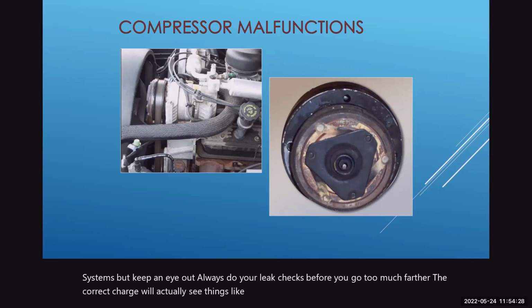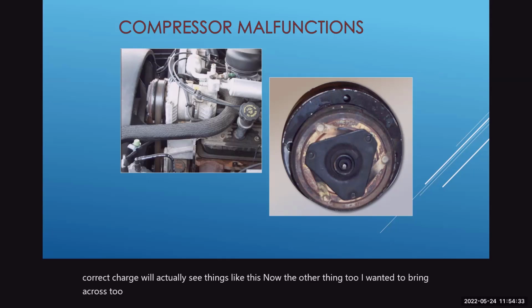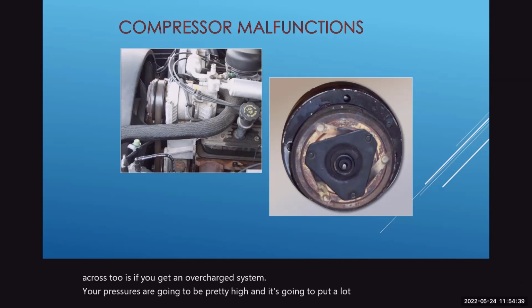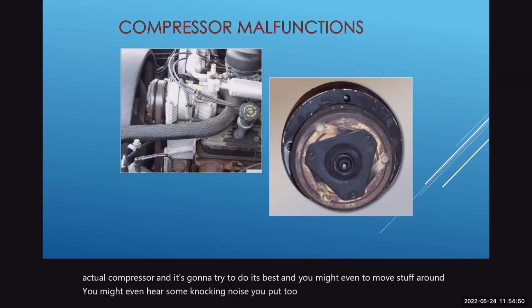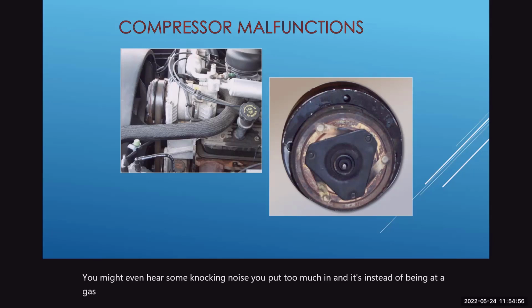The other thing I wanted to bring across is that if you get an overcharged system, your pressure is going to be pretty high, and it's going to put a lot of pressure on the actual compressor, and it's going to try to do its best. You might even hear some knocking noise. You put too much in, and instead of being at a gas state, it's going to be at a liquid state.